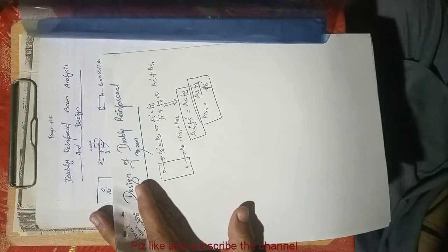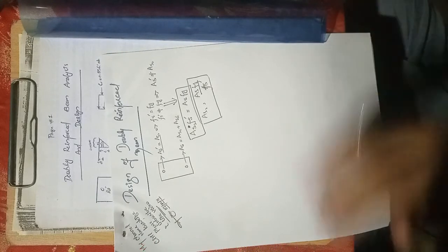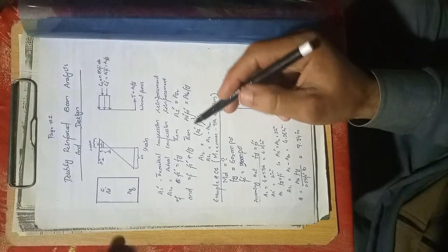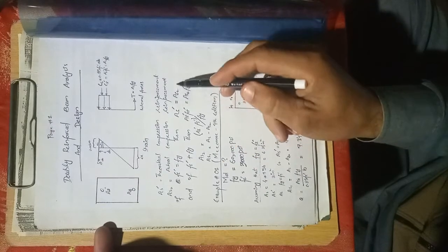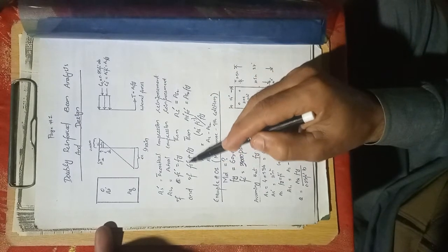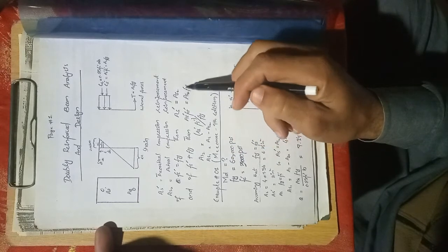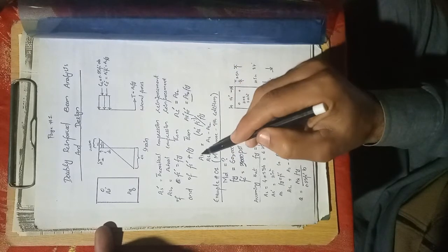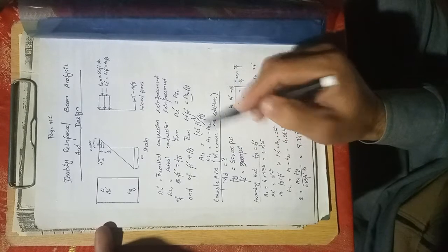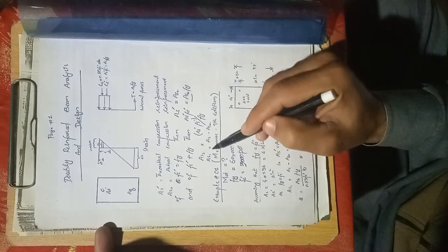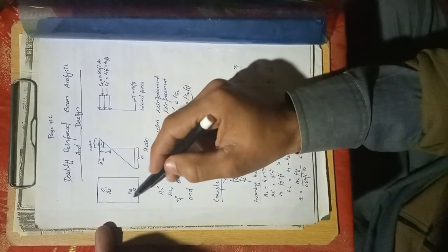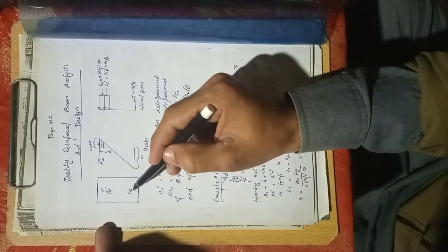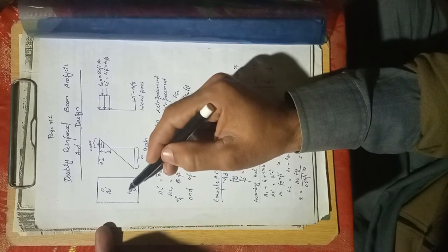So this is very important, and you must remember this condition. I already wrote this down right here. You see, when fs prime equals fy, then As prime equals As2, but when fs prime does not equal fy, then you have to use this relationship, and from it your As2 will be this one, and As1 will be recalculated as As minus As2. As is the total tensile reinforcement, right? And As is further equal to As1 plus As2.